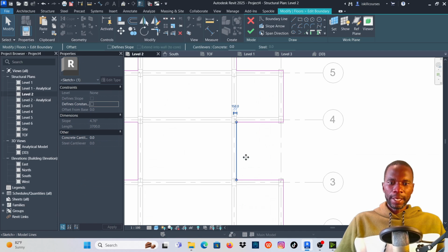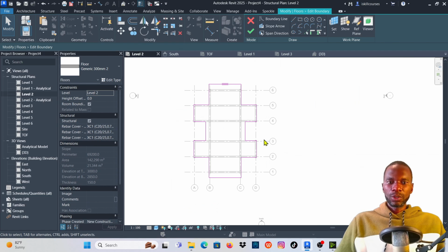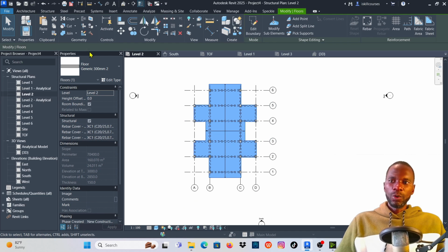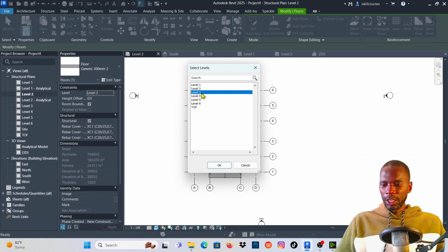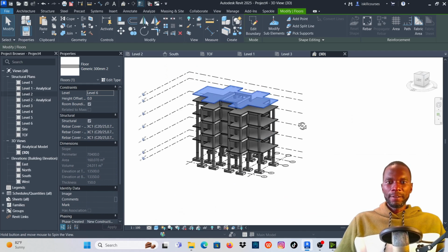Maybe even here the floor, there is maybe, you know, an overhang there, a cantilever a bit. You can do that. So I'm just trying to show you. So click there. Now I don't have to go to the 3D view. I can click on copy to clipboard, click on paste, align. Now I'm getting faster because you already know what is supposed to be done. Okay, up to somewhere there, click on finish. It's there in 3D. Go to 3D view, perfect.